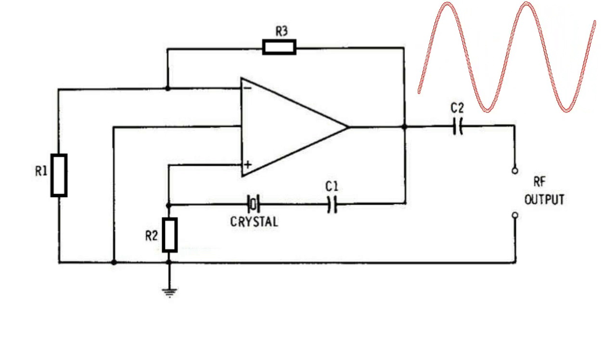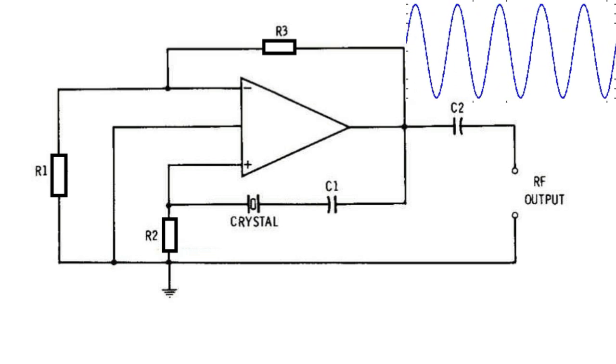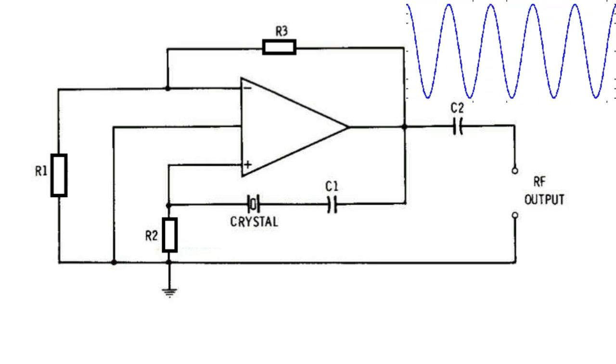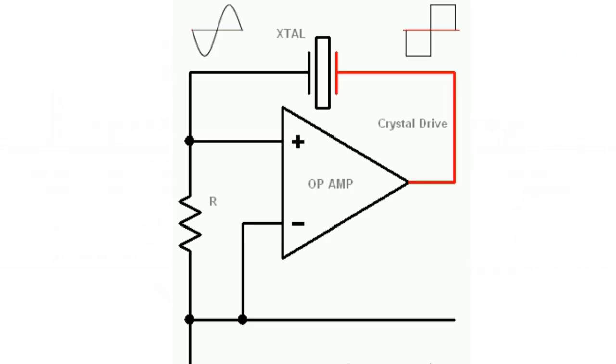The use of the negative feedback helps to enhance stability of this op-amp oscillator circuit and also helps to minimize the output signal distortion. Nevertheless, this could be totally omitted only when a high harmonic output is needed, for example, in many of the transmitter-type circuit applications.